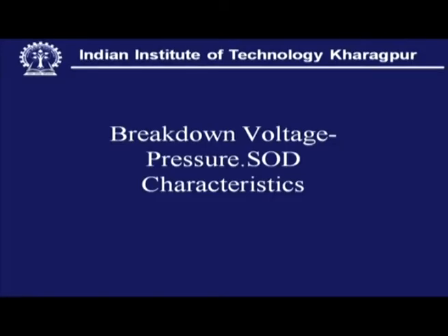Now, all these things are done. Whatever velocity or energy is gained by the incoming ion is a result of the electric field, and that field is created by polarizing this target, which serves like a cathode. So, here one graph is very important, not only from an academic point of view, but also for designing the sputtering apparatus or the sputtering device.